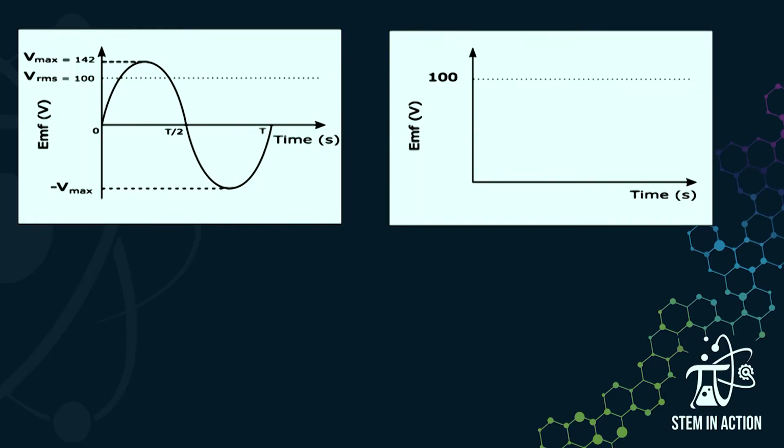So we need to go and find out what is the power that is generated in an AC circuit. So let's go look at some derivations using the same example. There are our graphs for a DC circuit showing the maximum voltage, and for an AC circuit showing VRMS. We know, and we've been told earlier, that VRMS equals Vmax divided by square root 2.